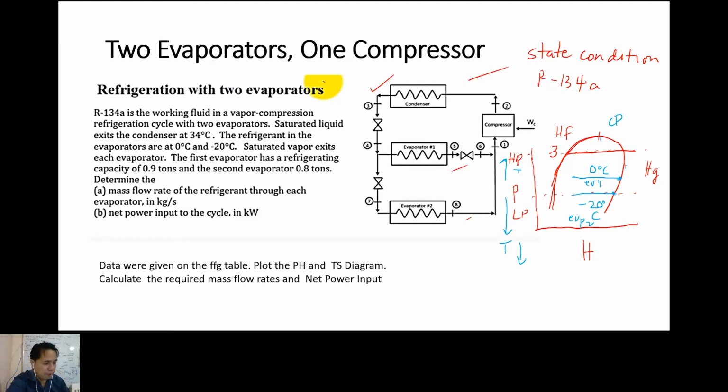So this is the evaporator line. Evaporator exit, saturated, meaning gas. So here, the quality is 1 or the quality is 100%. By percent it is 100%, by proportion it is 1. Now the question is, what is the quality here at point 3? Zero. So at point 3, the quality is 0.